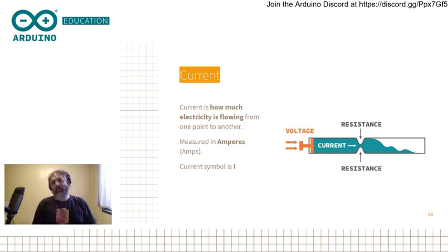When we talk about current, we talk about milliamperes. The current that an Arduino Uno pin will release will be at most 20 milliamperes, which is really not a lot. So you can barely turn an LED on or off. If you want to turn a motor on and off, for example, you cannot really do that from the pin of an Arduino Uno board. You need to use something else, and even less from an MKR 1000.